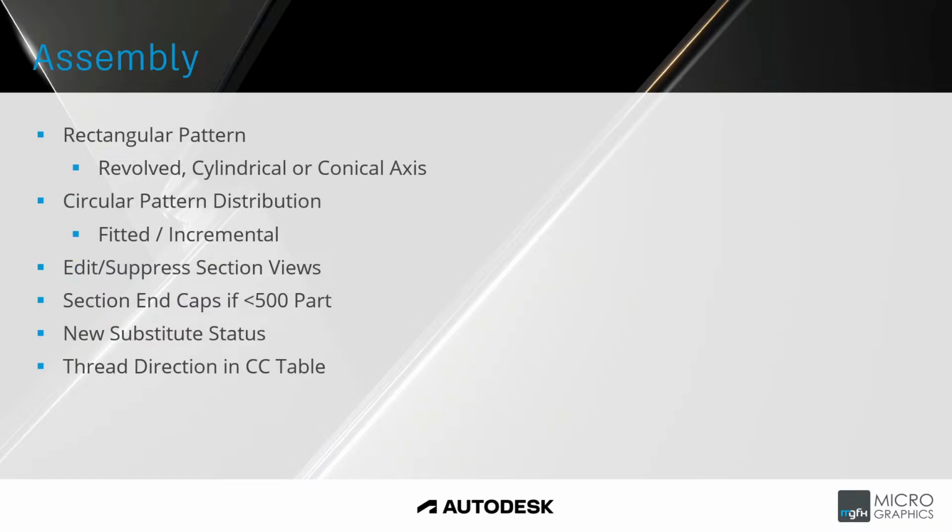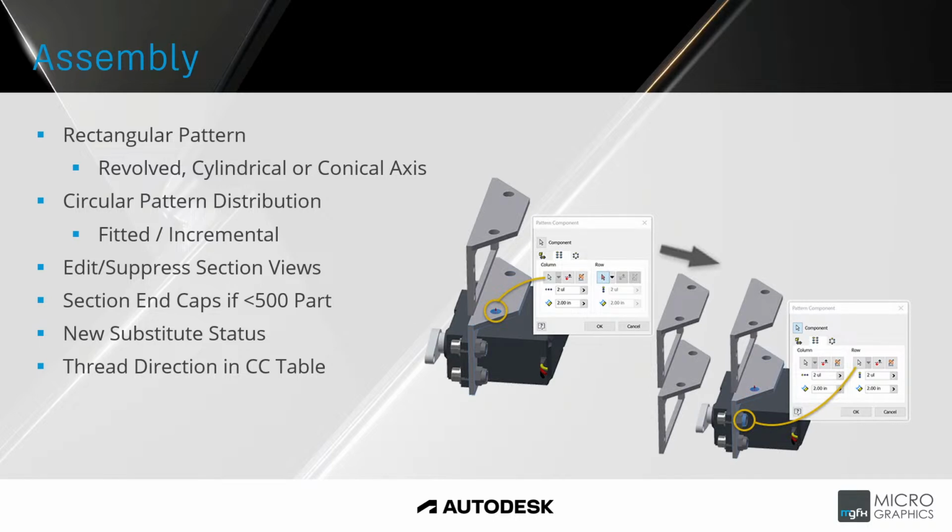So let's have a look at the assembly environment. First, we have improvements within the pattern commands within the assemblies. So the first up is rectangular pattern. You are now able to select a revolved, cylindrical, or conical face to then generate an axis for the rectangular pattern. So if you need to choose a direction for your pattern for rows and columns, you can now pick a revolved, cylindrical, or conical face.